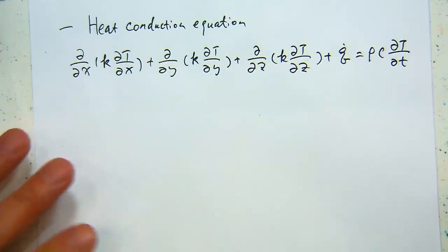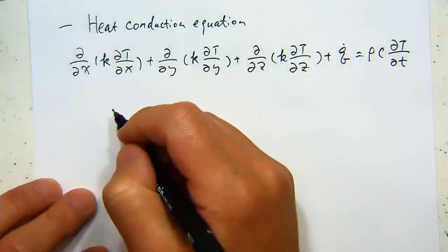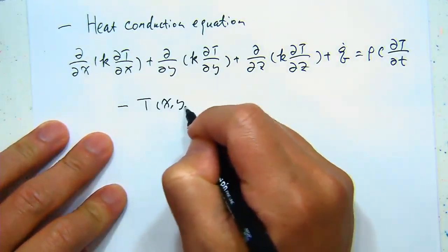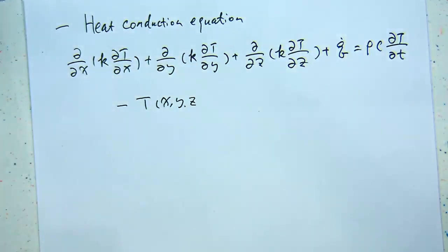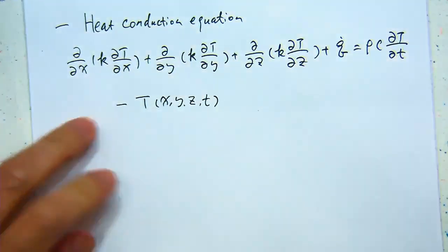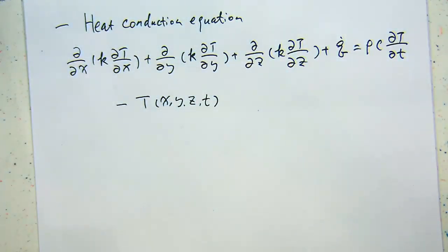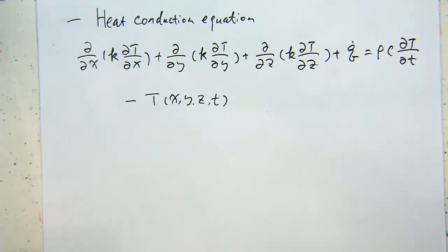So this one allows us to determine the temperature distribution within a three-dimensional medium if you're using Cartesian coordinates x, y, z, and also as a function of time. Right. So this is the most general case, and in the problems we are seeing in this subject, we mainly only deal with one-dimensional conduction, right? Even though later on in a certain problem we discuss, for example, the extended surface conduction, the heat transfer can happen in multiple directions, but the conduction we consider there is still one-dimensional.